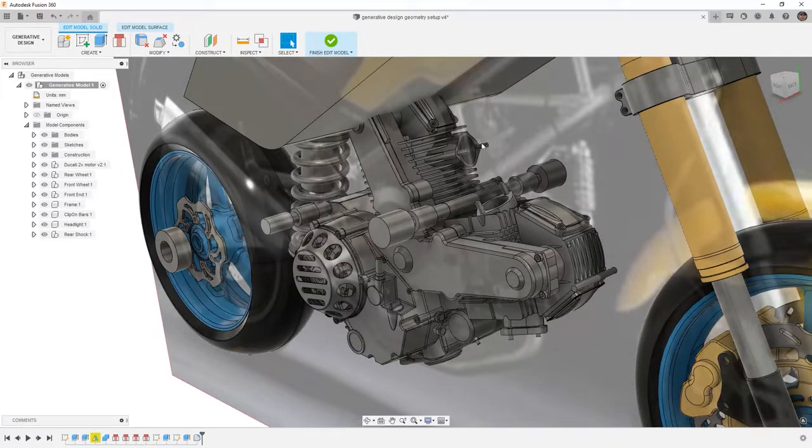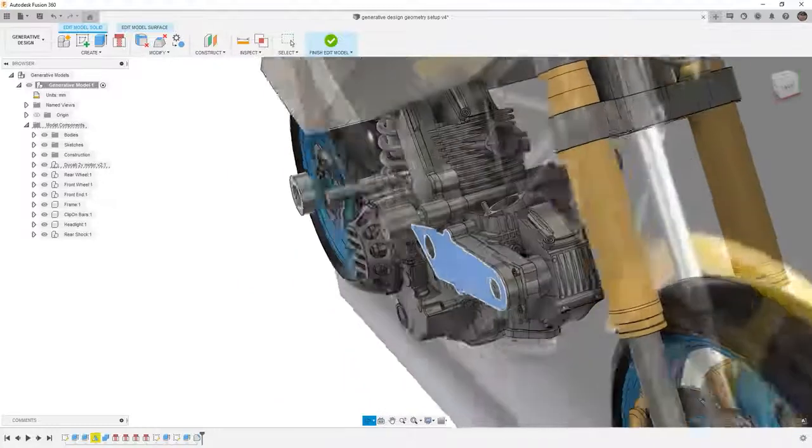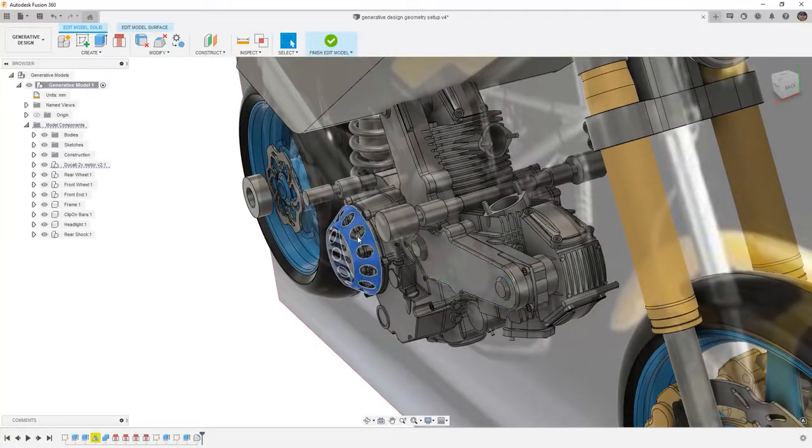The throttle bodies for the fuel injection system, the intake or airbox, there are a lot of components that just simply aren't there. So we need to pick and choose areas that we want to make a simplified version and some that we want to simply just select what's there. For example, this cover we could very easily select. However, the clutch cover has a lot of openings and components inside, and that will just complicate the calculations.